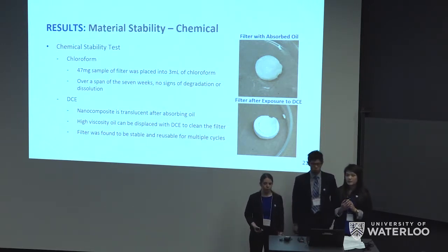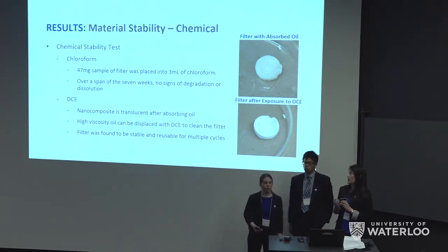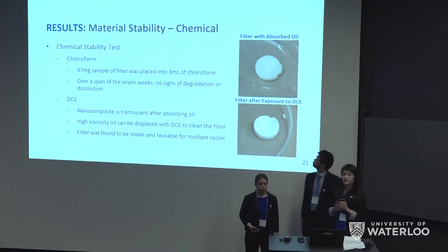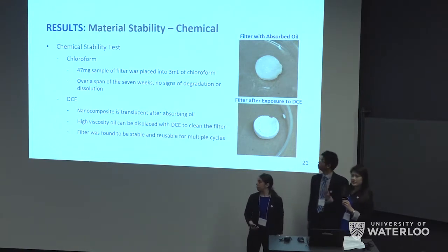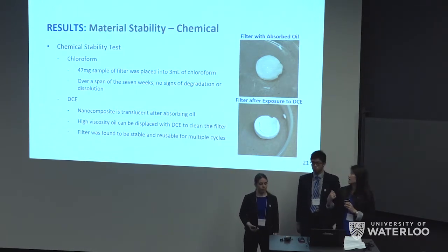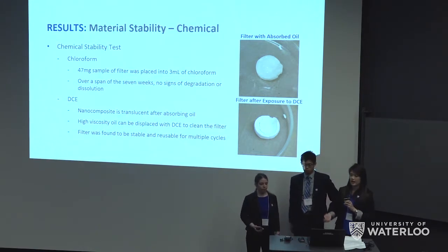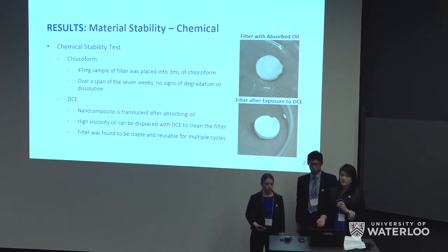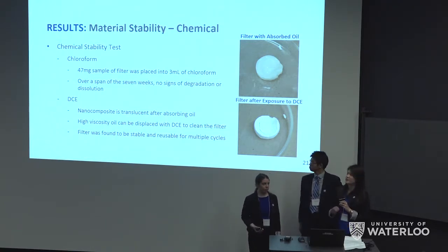With DCE, we were also interested in seeing if we could clean our material with it. On the top there, you can see the filter has wetted a lot with oil, so it's slightly translucent. After we expose it to DCE, you can see that it's white again. It's no longer translucent. The DCE had displaced the high viscosity oil. So not only is it stable in chlorinated solvents, but it can also be dried, cleaned and reused.